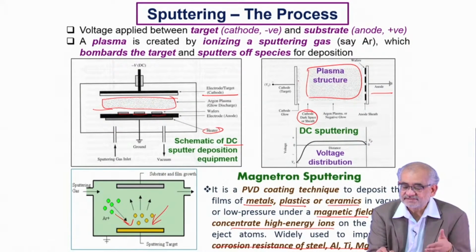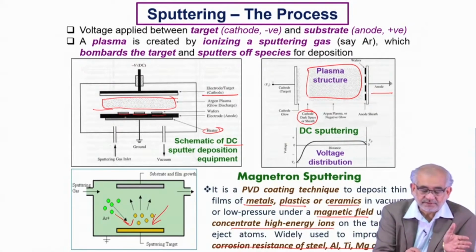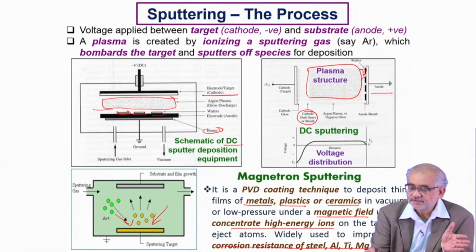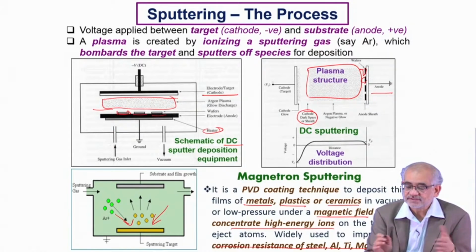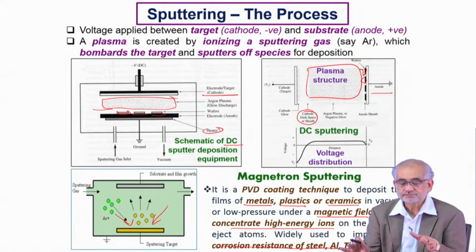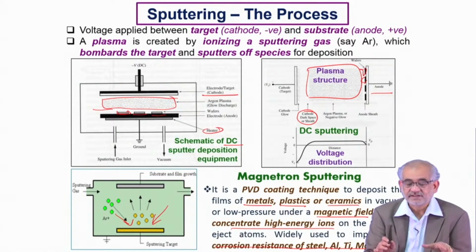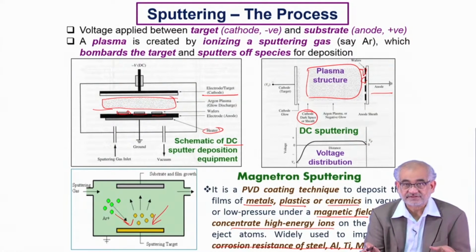The exact thickness and the location and the width of this region largely affects the overall coating thickness and the uniformity of the coating. One other thing that is very important is that if you look at this substrate here or this substrate here, they are tiny, much smaller compared to the overall dimension of the plasma that you create, and this is how you can make sure that there is uniform coverage and no shadowing effect, no non-uniformity.